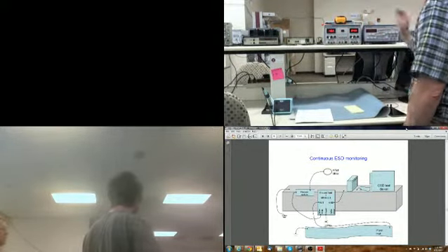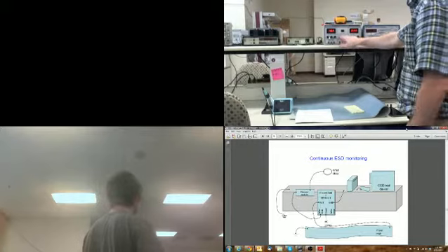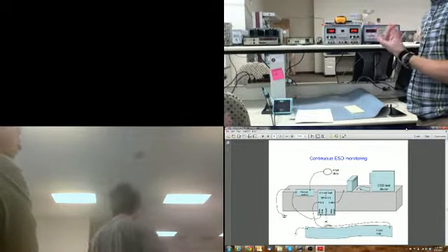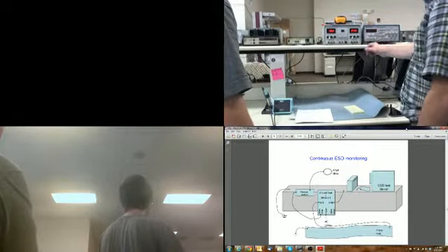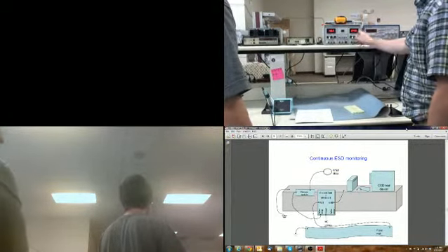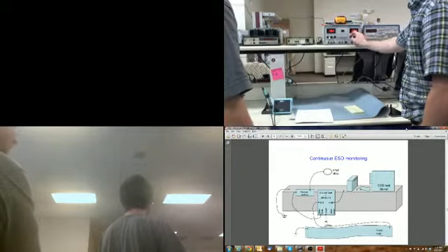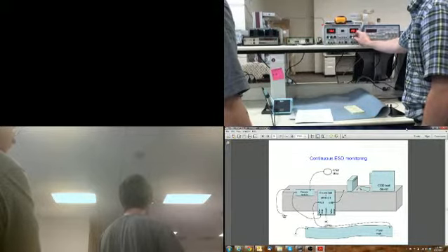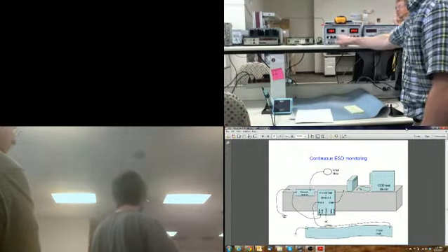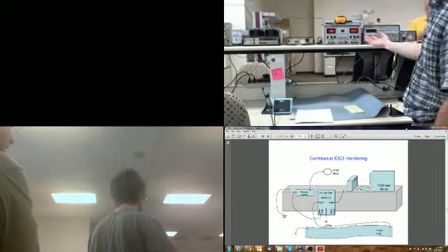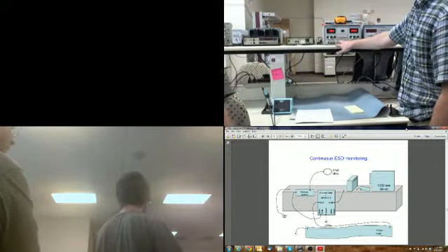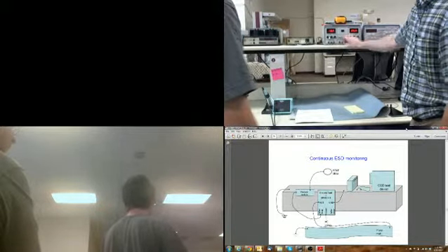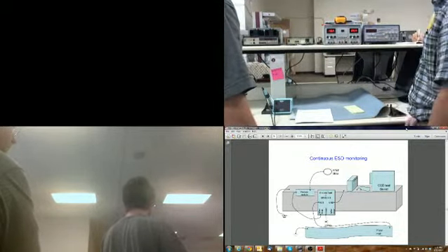Now, the normal mode for this power supply is all the buttons will be out, okay? In the non-depressed position. In that position, you have three knobs over here: a voltage knob, and a fine voltage knob. The fine voltage just increases it slowly. You have a current knob, and you have two sides. This is a double supply, so you have one here, and then you have one in the middle. The one in the middle goes from 4 to 6.5, and it's just a small little supply. It doesn't have all the features that the ones on the side do.